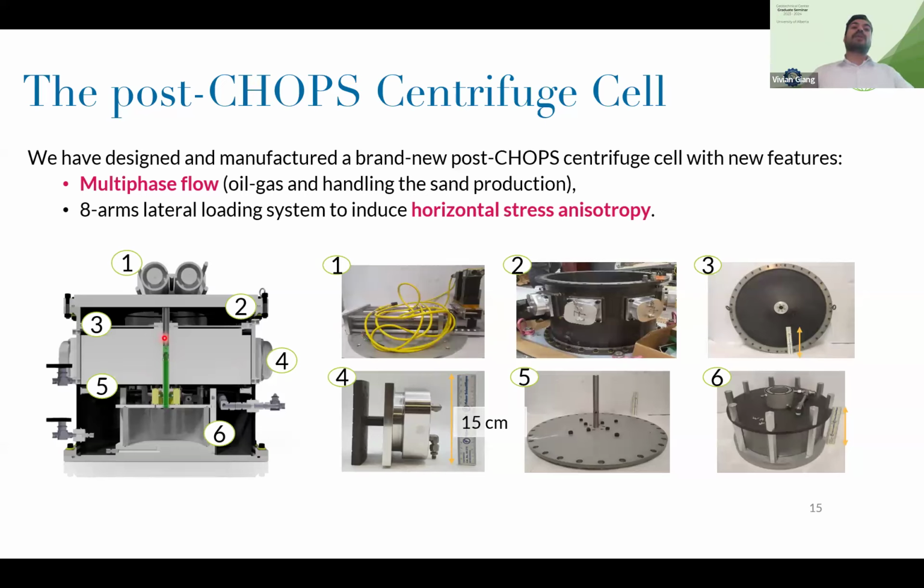So you have a wellbore that we can operate remotely, because this is going to rotate at 30 Gs. 30 Gs is 120 RPMs, which means twice per second, you are going to have a system whose weight is around 500 kilograms just rotating twice per second. So clearly you cannot go down and open a valve. So we created a system to open this wellbore in the middle remotely.